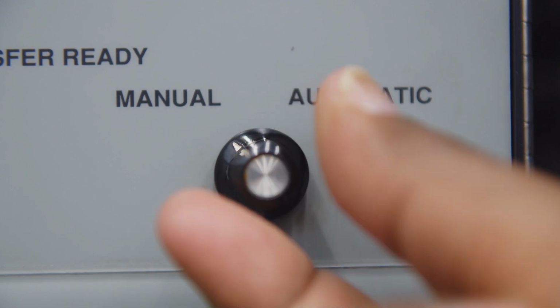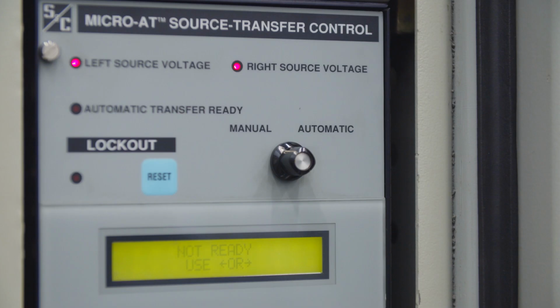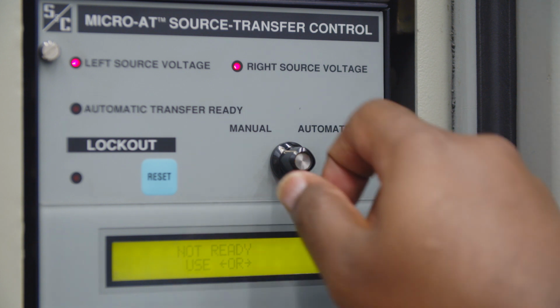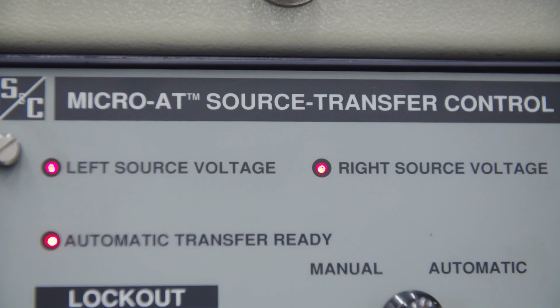Once in manual mode, the primary source can be closed and the secondary source opened, according to your company's standards. After switching and any additional configuration, put the Micro AT control back into automatic mode. The red LED Automatic Transfer Ready mode lamp should now be lit, and the control should be ready to operate